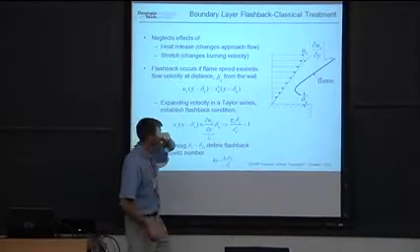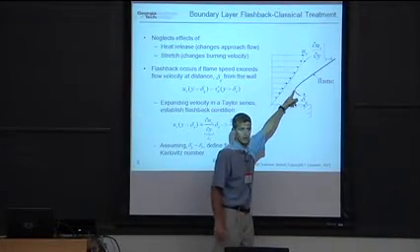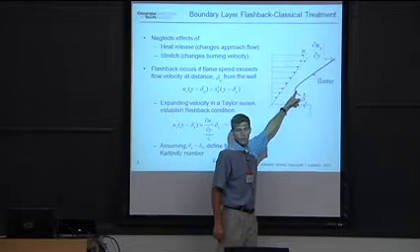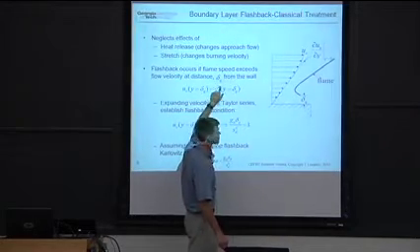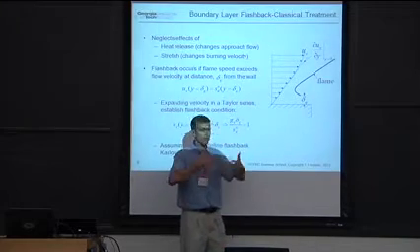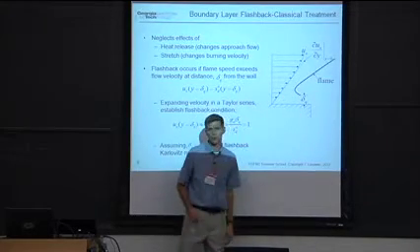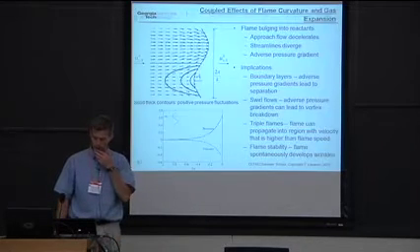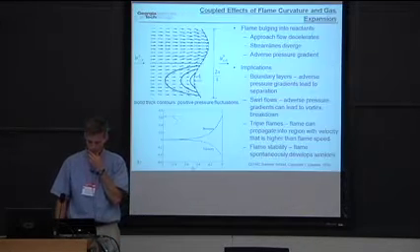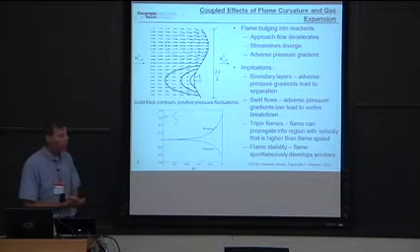The other reason is stretch. This flame is very obviously positively curved. Stretch changes the velocity. So what should this flame speed be? It's a function, and it's part of the problem to figure out what the curvature of the flame should be. So I want to show you that. First I want to talk about some hydrodynamic influences, and to do that, I want to back up a little bit.